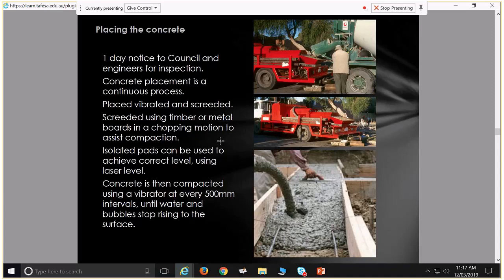But you also have to think about the practicalities. How are you going to get concrete to site? When can you be doing that? How is that all happening? So we've got our concrete there. We've got everything organised to the T. Things are going ahead properly. Concrete's getting placed. It's the right slump. It's the right mix, etc. We're getting it all vibrated down into the forms.